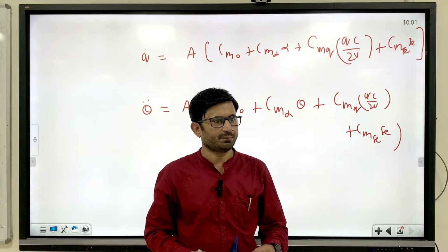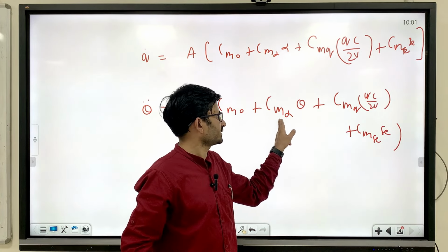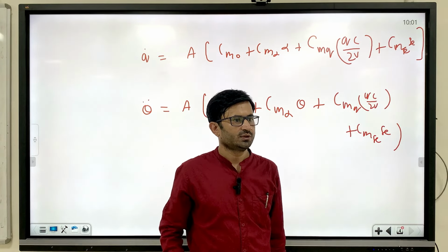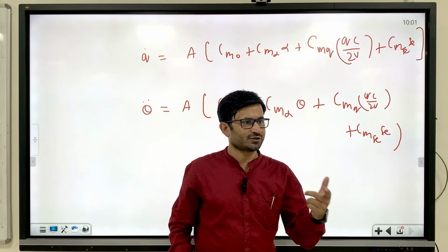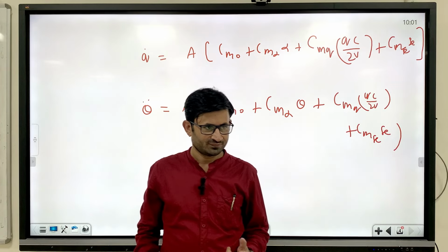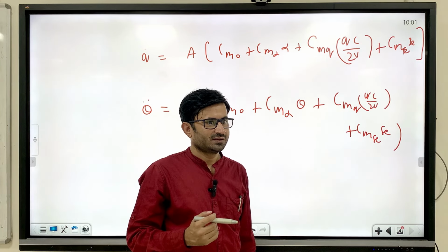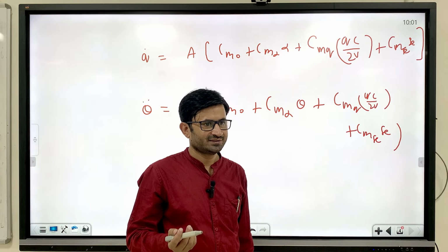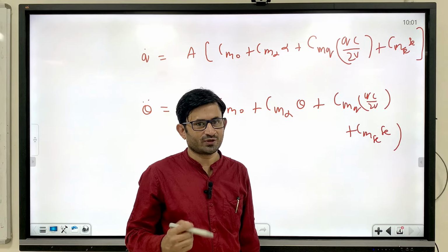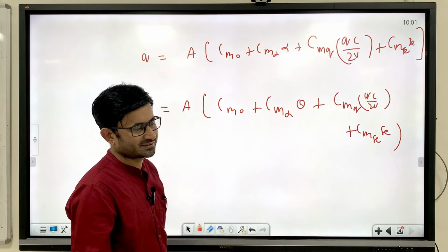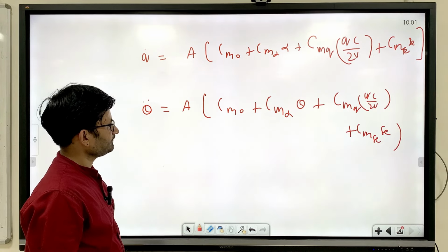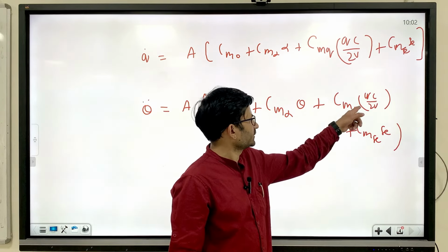So CMQ is a damping derivative. This is the pitch stability derivative, and this is a damping derivative. So this decides how much natural damping you are having. You have studied Omega n and zeta, right? So if the CMQ value is high, the zeta value will be high. You can relate this.